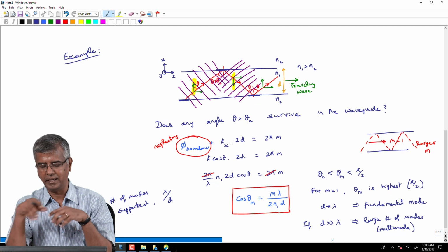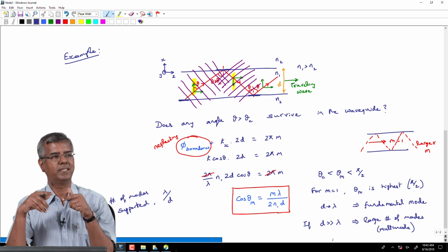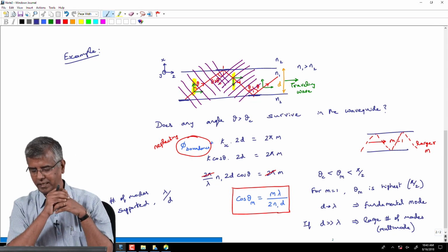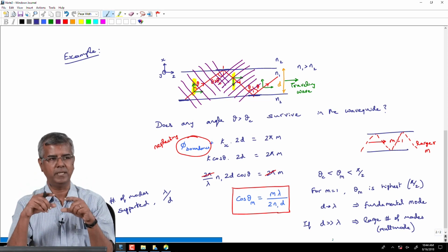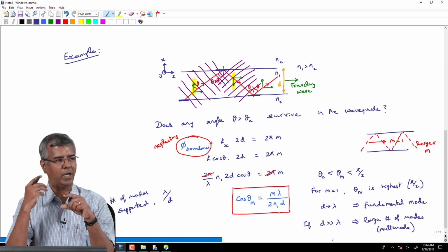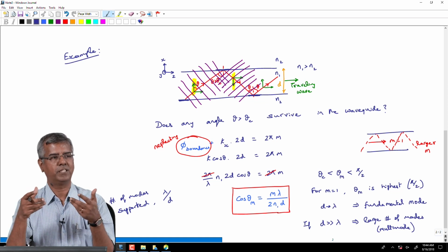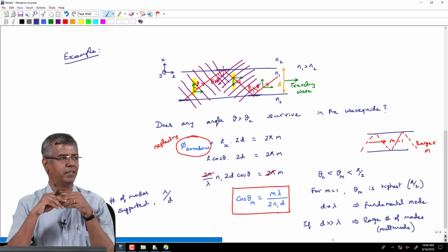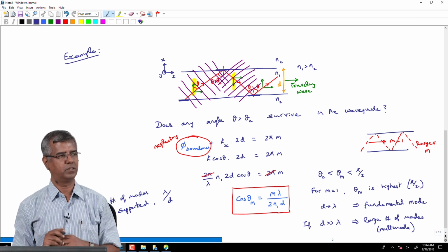But what we are considering here is an optical fiber, which is a dielectric cylindrical waveguide, okay. But the principles are the same. Since you have boundaries in the structure, you have this concept of reflection that comes into the picture, and whenever you have reflection, you have interference, and that interference actually gives the concept of modes of the waveguide, okay, right. Higher the order, more steeper the bounce, okay.